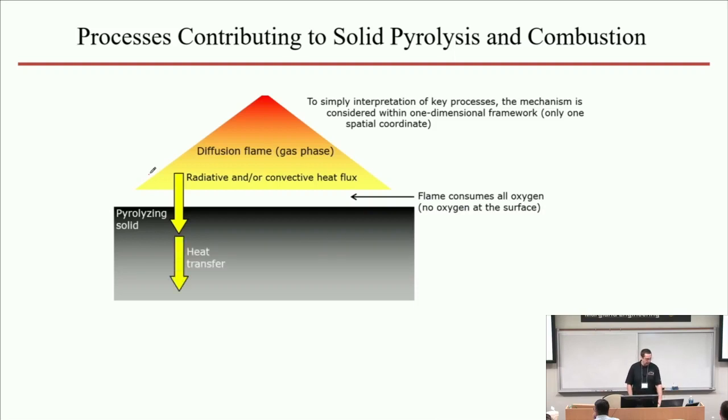If we focus on that, the other thing that happens in a solid, and this is what we observed in the initial slide, is that there is a considerable heat transport from the part where the energy is absorbed into the depth of the solid. For solid thermoplastics, that heat is primarily transported by conduction. But if you look at materials that are porous in nature, then radiation can play a significant and sometimes dominant role in this transport as well. In addition to that, we have the radiative heat loss that was mentioned on the previous slide.